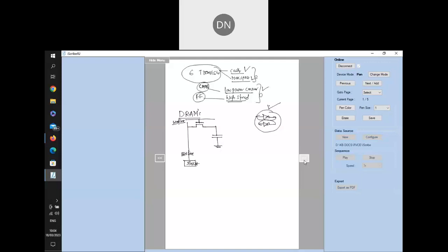Now, whenever you want to write 1 to this cell, the transistor is enabled and the 1 is applied here. Then what will happen? It gets charged to 1. So the plus 5 volts or 3.3 volts remains in this capacitor. If I want to store the 0, apply the 0, then it will be charged to 0 voltage. So the capacitor contains the logic 1 or 0 information.